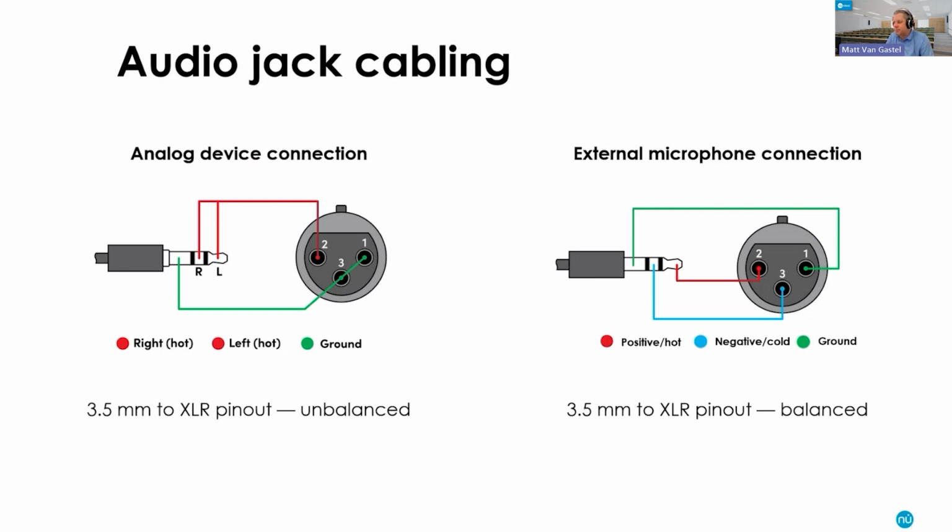These are unbalanced inputs. The maximum cable length is suggested to ensure minimum noise coupled to the signal. If you do have a concern about noise or you do need to run a little longer, I recommend changing these to a balanced signal using a transformer or similar type device. And this will allow you much longer runs, much better protection from things like noise.